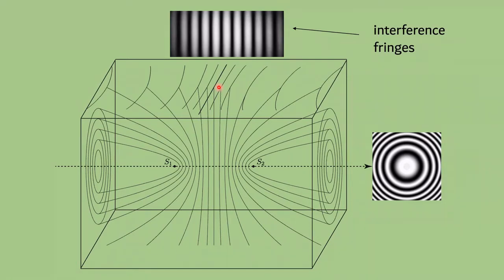You can't do it with a ruler, that's for sure, because a ruler will get you to the nearest millimeter at best. Some of you have used a vernier caliper, which will get you easily to 1/10 of a millimeter, or even a micrometer, which will get you to 100th or even 1,000th of a millimeter. But we're going to see how interference of light allows you to measure something even smaller than that. And that technique is called interferometry.